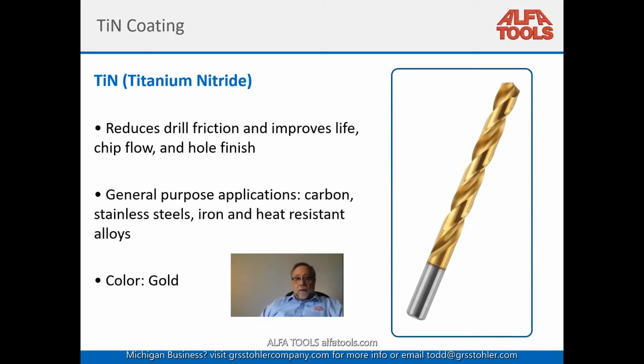Well, it's going to last longer. It won't break down as fast. The coating itself is a very lubrous item, so it keeps the heat from building up. And it's a barrier. They're like 4 microns thick if this is done properly. So you don't change the diameter of the drill, but it's a very thin film coating that adds lubricity and helps you get more tool life.